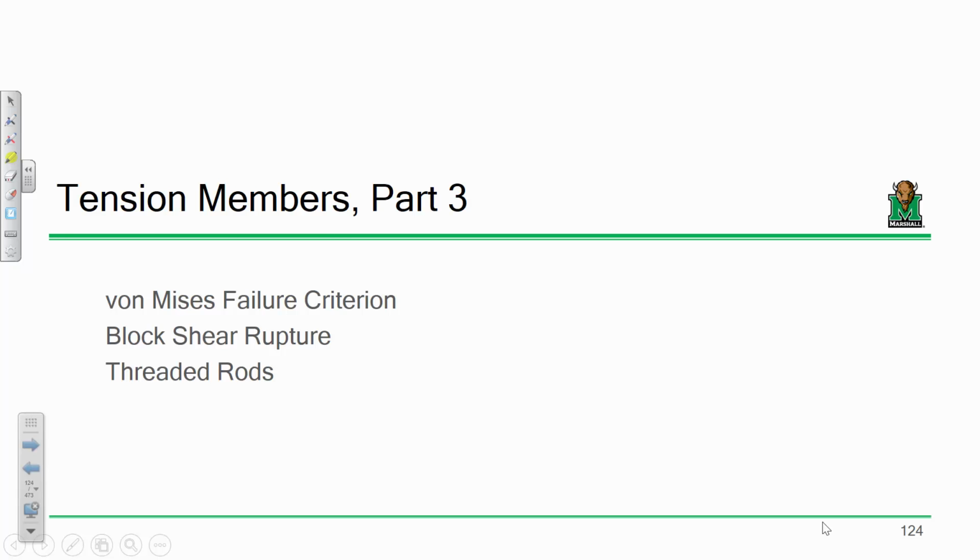Yeah, this is good stuff. I like this. Are they planning on expanding that bridge, like making it wider to make I-64 bigger? I don't know. Now, it is common practice when you're designing bridges on large volume roads that you might have two 12-foot lanes and two 8-foot shoulders, really wide shoulders.